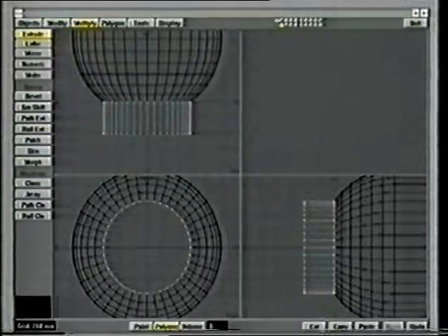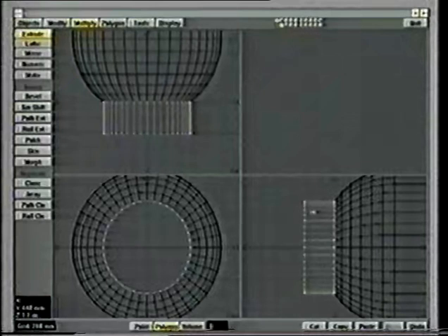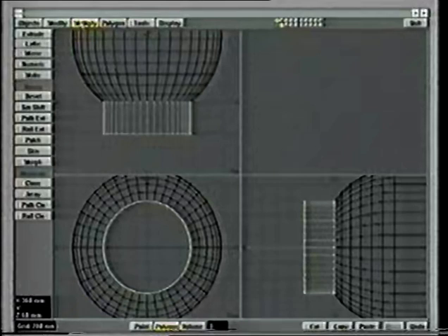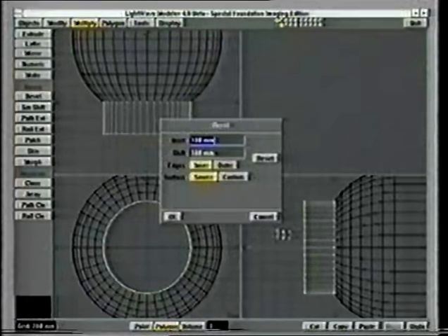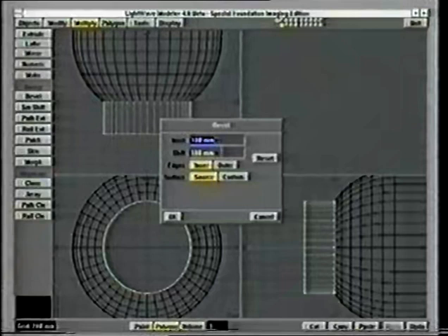So now what I want to do is create the rim of this nose piece, the rim of the docking area, and bevel becomes an extremely useful tool at this point. So I select the front polygon here, multiply, bevel. Now, judging by the grid size here, 200 millimeters, probably 10 millimeters on each would be sufficient.